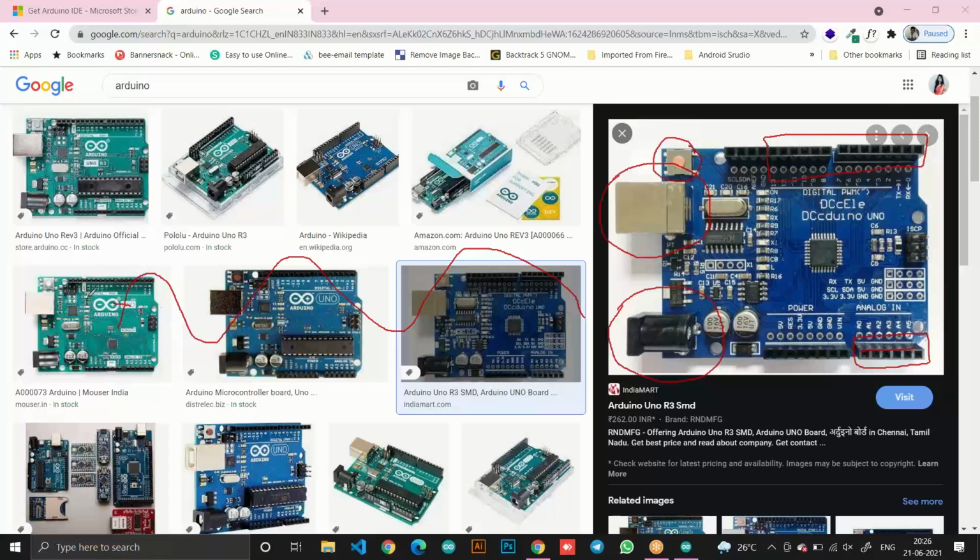For example, over here we can have a value of 100, over here there may be a value of 200, over here a value of 500. According to the requirement, the analog sensor's value is set. Basically, analog sensor values vary from 0 to 1023.